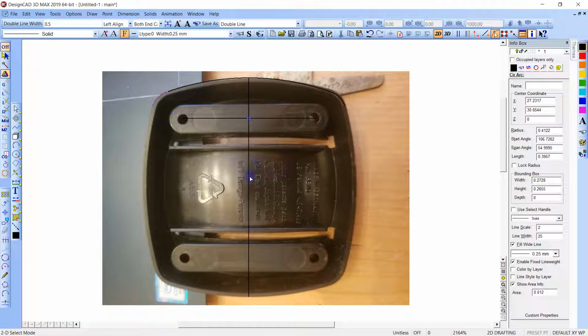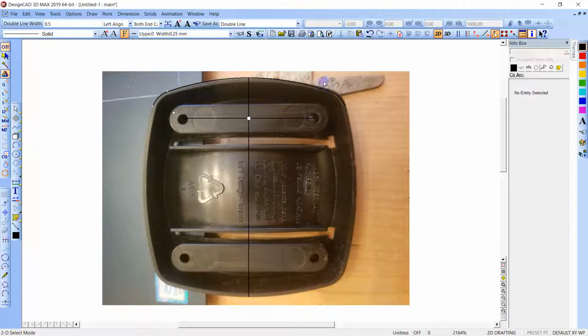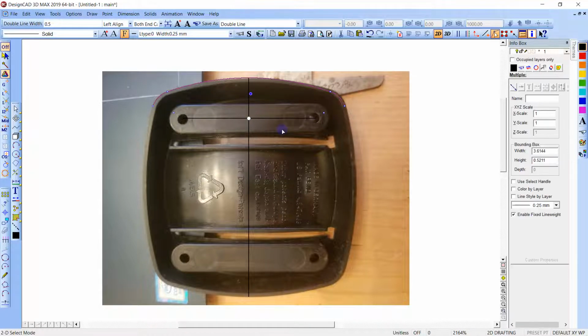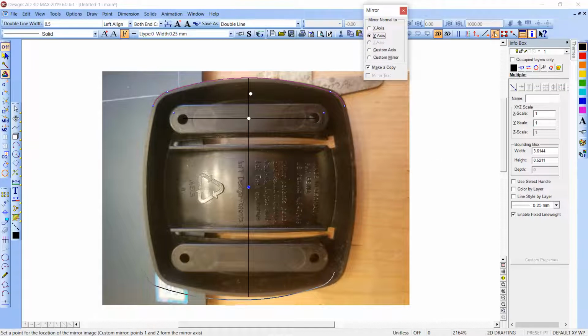So now I have a center here. I'm going to take this radius, these 3 pieces, and Control H, set them in the middle of this line, Control K, enter, and then reflect that in the vertical axis. So divide symbol Y, right click to the center.